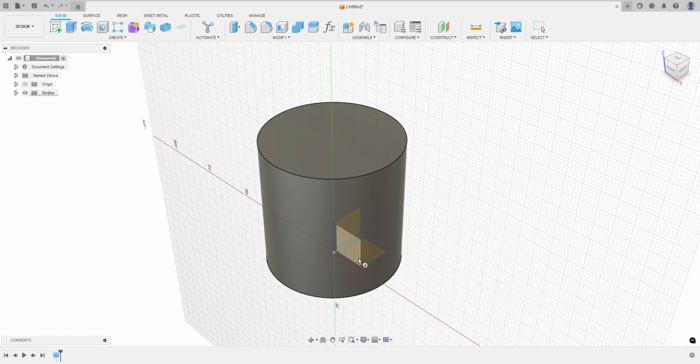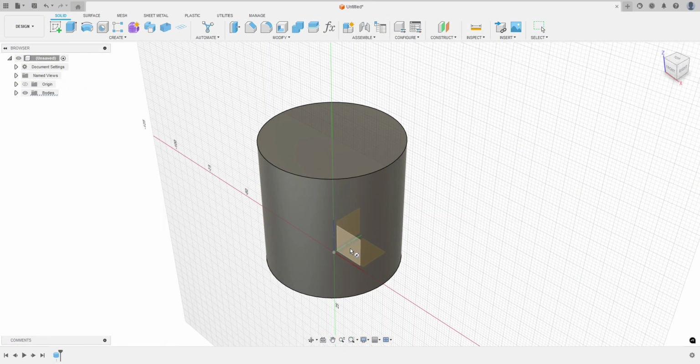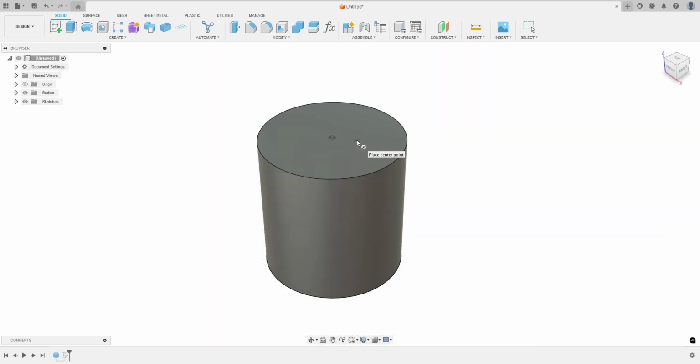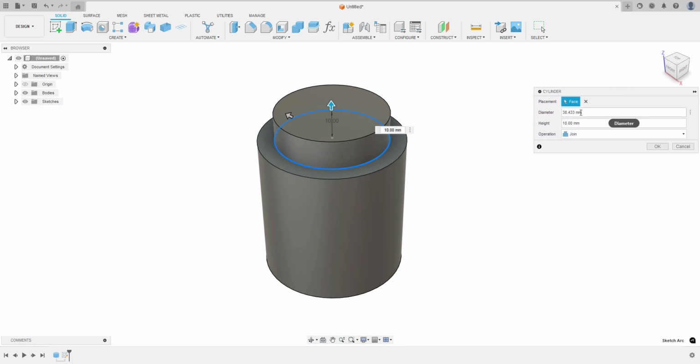If you don't know, you don't have to choose one of these planes when you try to create these solid bodies. You can also pick surfaces. So I'm going to choose this surface. I'll click on the origin and drag out. And like last time, I will just do everything from right here. I like doing this because I can actually make this longer, especially when I want to type out a formula. So the height, we'll just keep at 10 millimeters. For this jar, the height of these threads will always be 10 millimeters. You can make this height whatever you want.